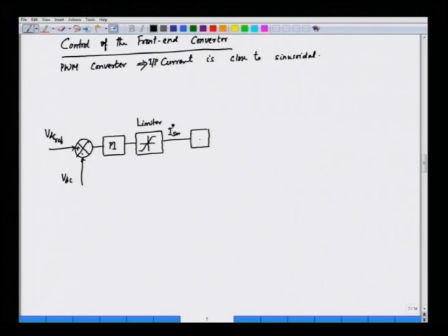This we multiply with omega Ls, the reactance, and then for one phase, if we talk about only phase A, we multiply this with sin(omega t plus pi by 2), and then we have the voltage from the source, Vm sin omega t, and we generate the phase A reference, VCA reference. Now, this is basically for phase A.